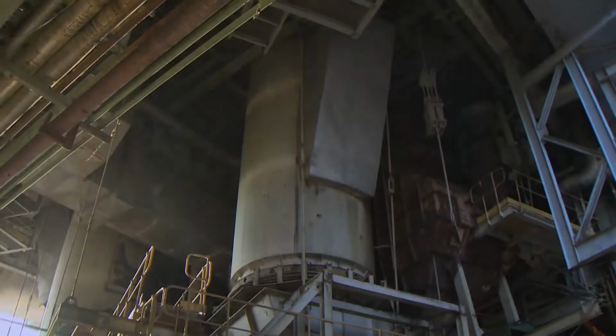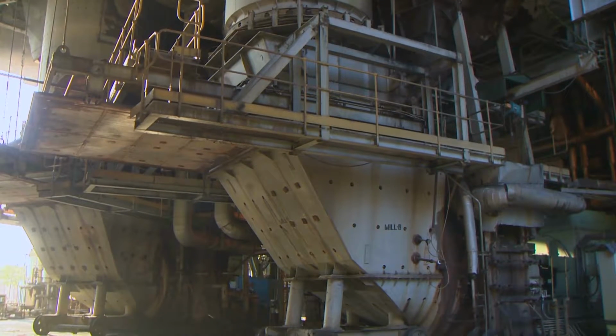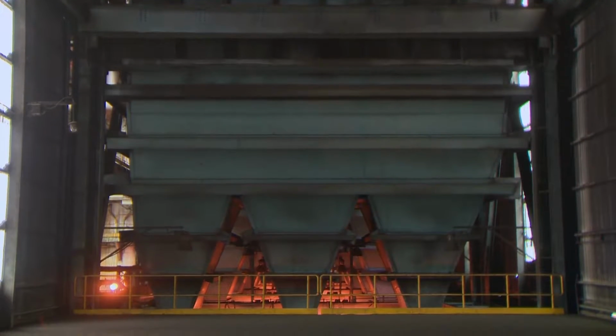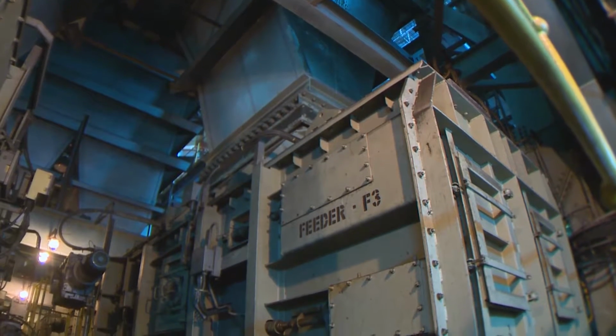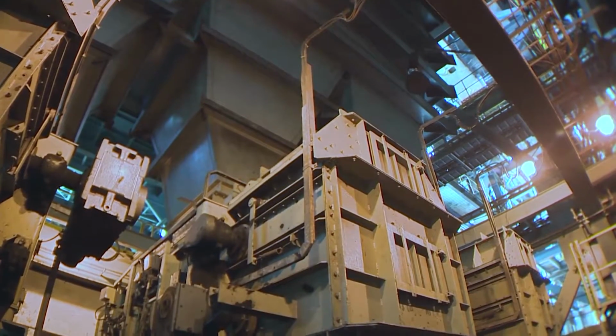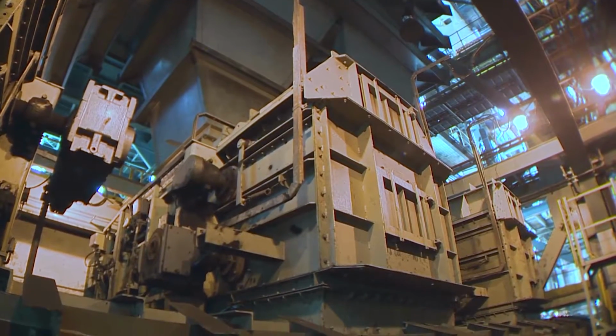Firing system. Tangential suspension firing system is adopted in these boilers. The lignite stored in the boiler bunkers is transported to belt conveyor by plate belt feeder. The lignite quantity can be varied by adjusting variable frequency drive motors.